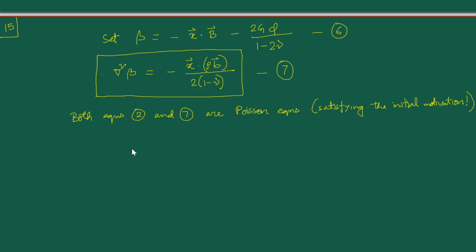which was the Helmholtz displacement potential. That representation involved the phi and the capital omega. We have done a lot of algebra, a lot of clever tricks, used vector identities and whatnot, and arrived at two Poisson equations involving the b vector and the beta. We solve that, and we find our answers for beta and the b vector.